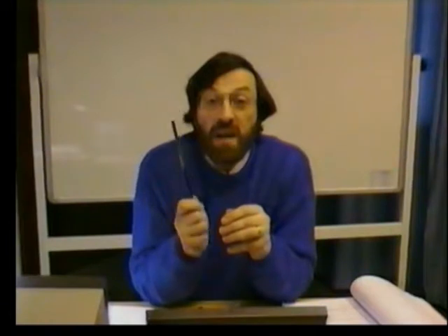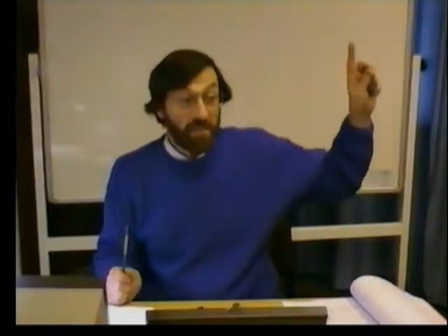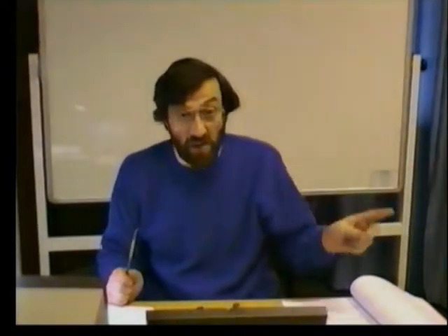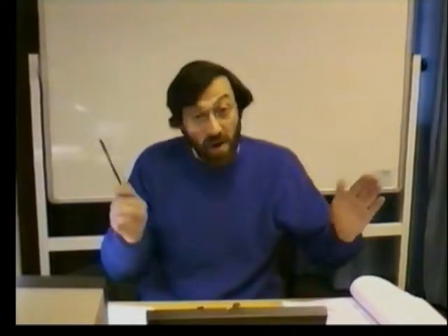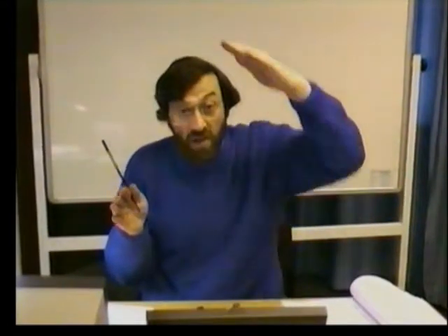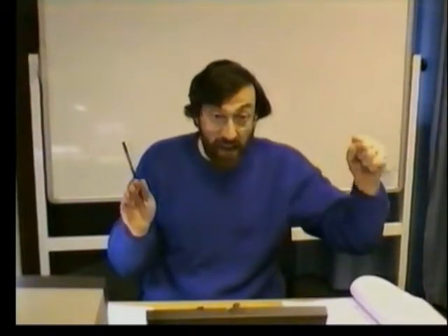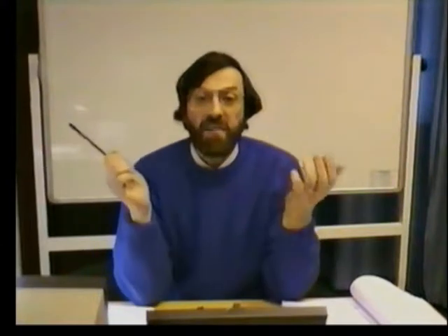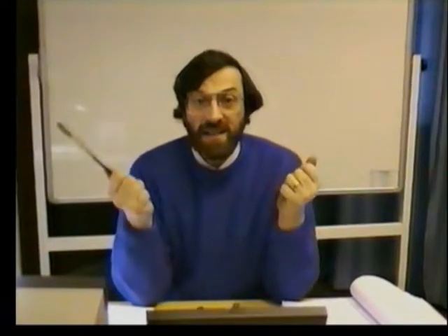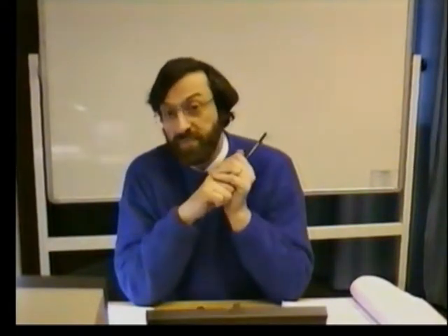Now there's another characteristic that's very important. Time. You never respond to things instantly. You're always looking at history. It's taken time for the transducer to get the signal, to convert it, to transmit it, to get to you, for you to think about it, to run your program, to do something. There's always a time delay, by which time things have got worse. So you're correcting an error that you believe was there, but because you've taken so long to do anything, the error has deteriorated and got worse. You could never respond to the correct, true, instantaneous error. It's always delayed in time by a very small amount.